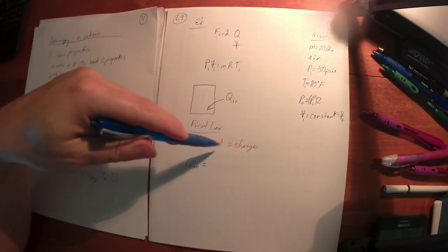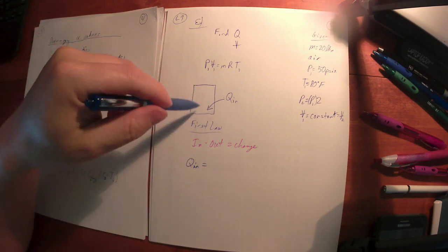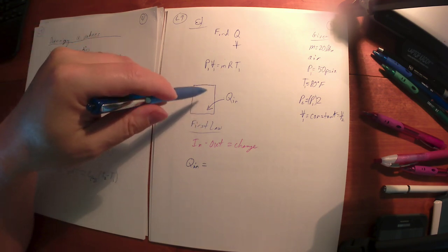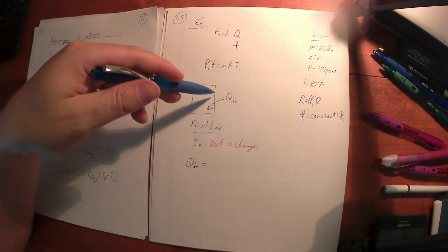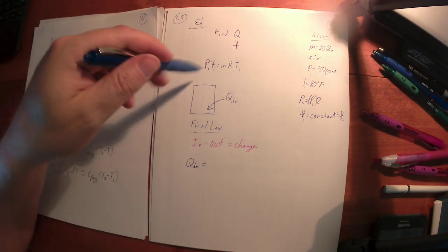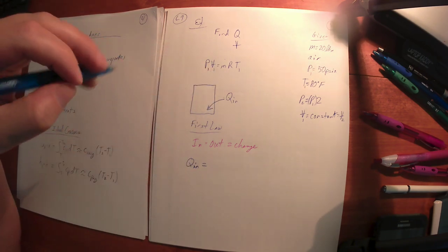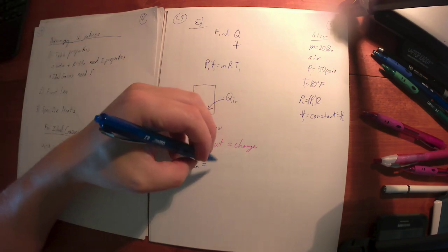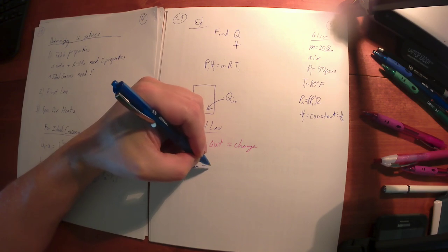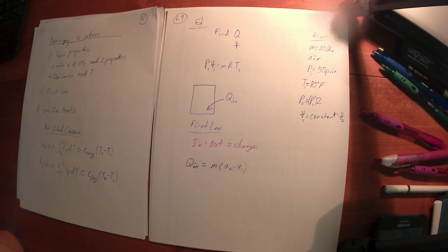You can write the big long equation and cross out the things you don't want. That's fine. Or you can just draw your system, just like you would in a statics or physics class. Draw your free body diagram. Draw everything that's attached to it. In those classes, that's forces. Here we're talking about energy. So draw your system and draw the energies crossing the boundary. That is your entire left-hand side of the equation. Add the ins, subtract the outs. Here I just have heat in, so that's my entire left-hand side. It's a stationary system, so the only energy that's going to change is the internal energy. There's my first law equation.